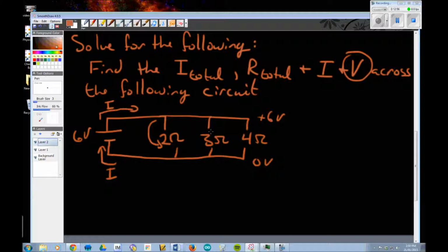Let's imagine that none of the other 2 were here. What would the voltage drop be across here? 6, right? If you think about it, that should make sense. If you think about this as a parallel plate system to which we've added pathways for electricity, the charge that's here is only passing through here. So it's got to be passing through a potential difference equal to what it is from here to here, a delta 6 volt voltage difference. So each of these pathways has charge that carries the same amount of energy with it as it travels through here.